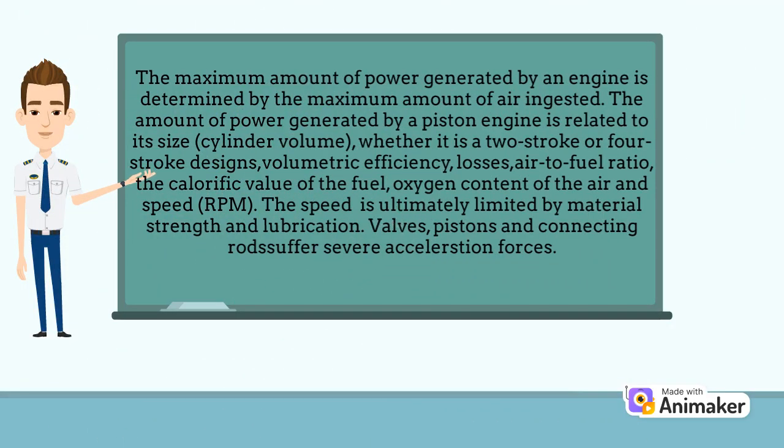The maximum amount of power generated by an engine is determined by the maximum amount of air ingested. The amount of power generated by a piston engine is related to its size, cylinder volume, whether it is a two-stroke or four-stroke design, volumetric efficiency losses, air-to-fuel ratio, the calorific value of the fuel, oxygen content of the air and speed, RPM. The speed is ultimately limited by material strength and lubrication.